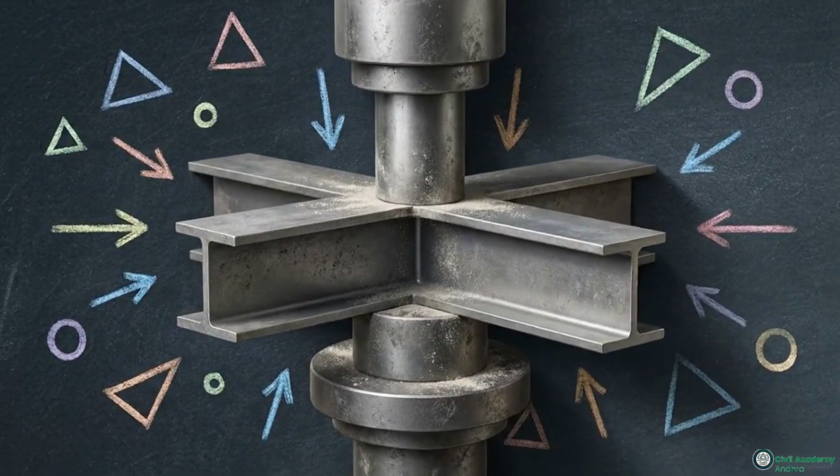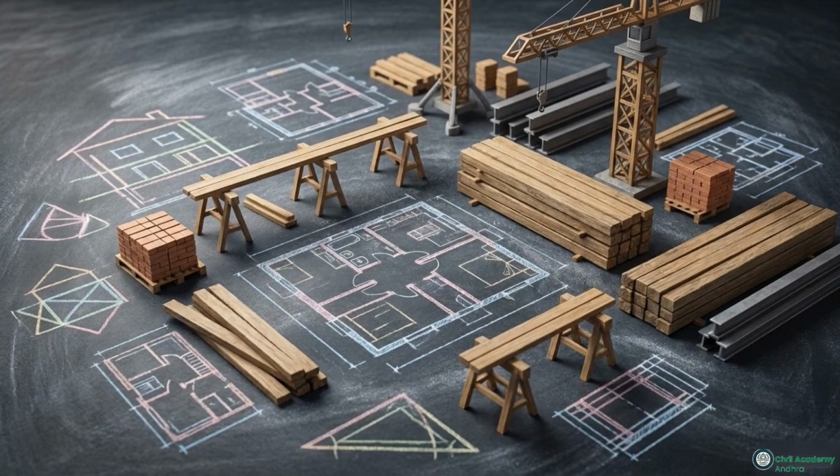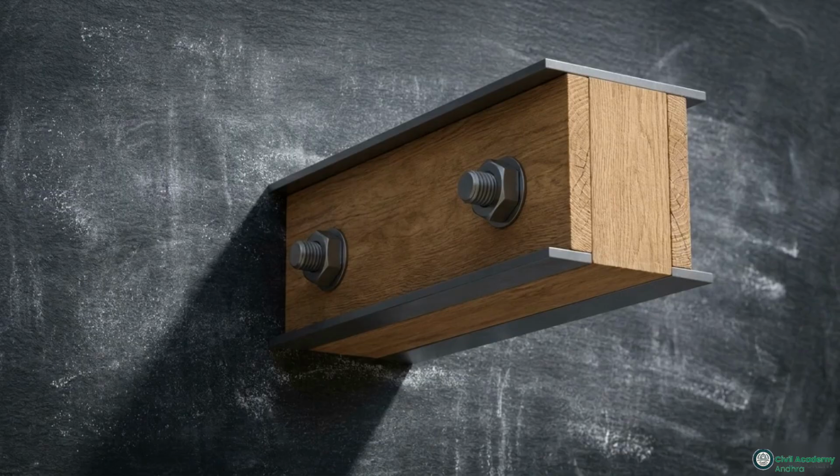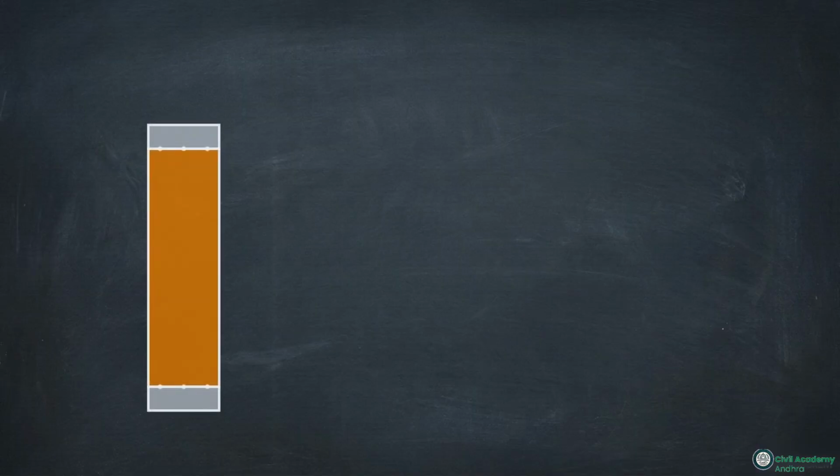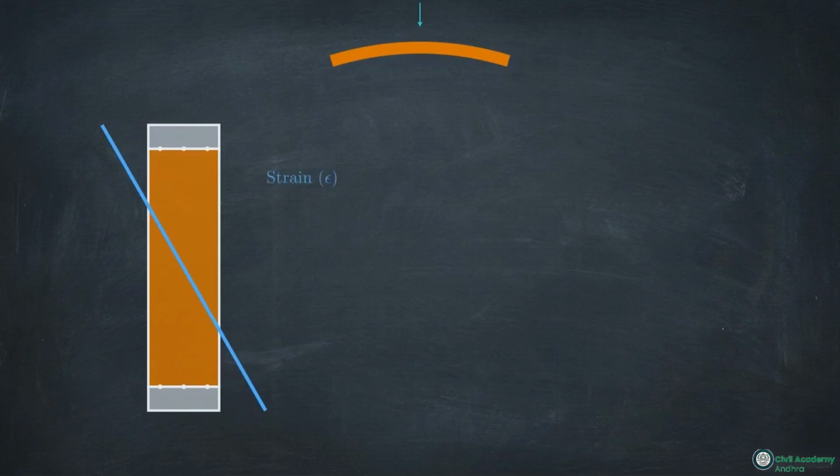In practice, engineers frequently encounter composite or flitched beams, where a weaker bulk material like wood is reinforced with plates of a stiffer material like steel. Because these materials are bolted or glued tightly together, they are physically constrained. As the load is applied, both materials bend with the exact same radius of curvature, creating a single, continuous, straight strain profile across the entire cross-section.